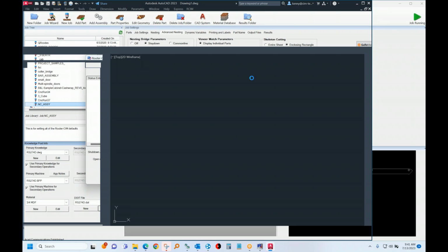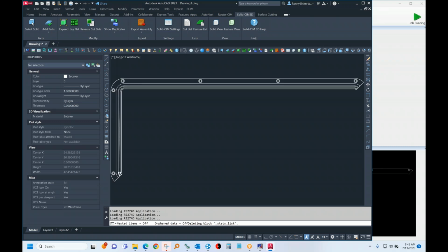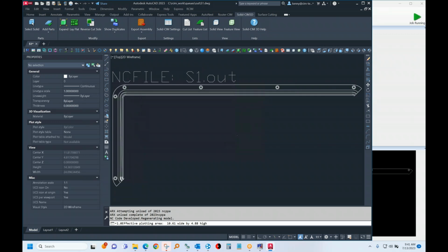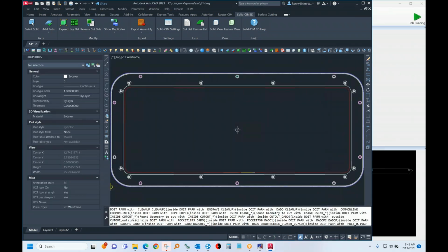we'll get two-sided nesting. We'll do all the front side and then all the back side. You put the sheet on the table upside down, it does the backside operations, then trims the edge of the sheet and flip it over, and it does the front side operations.